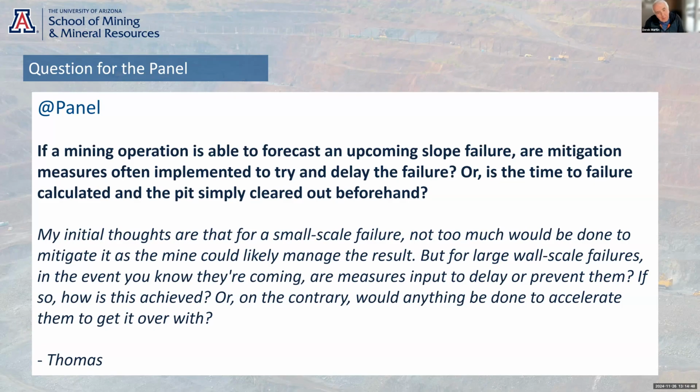I think also you have to be careful with small scale failures, because that's the definition of small scale. At least in the pits it's typically a bench, or a double bench, so often you will find equipment like a dozer that's cleaning the bench or something that's mining the bench will actually get partially buried, and the safety becomes the big issue. So the risk always has to be evaluated against the consequences, of course. And small scale failures can be detrimental to the operations just as the big ones can.